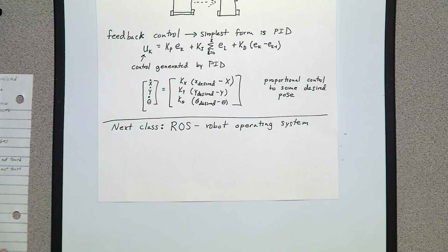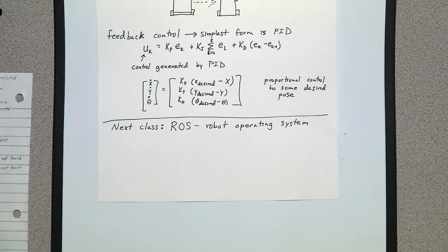Okay. So any problems so far? Yeah. So on task 2, where we have to connect to the ROS master with our phones, I'm having trouble actually getting to that. I've gotten to the point where, when I start up the robot, I get the IP, and then I put it in the app on the phone and connect it to the Wi-Fi, and then it just stays. So you're connected to the hotspot? Yeah.